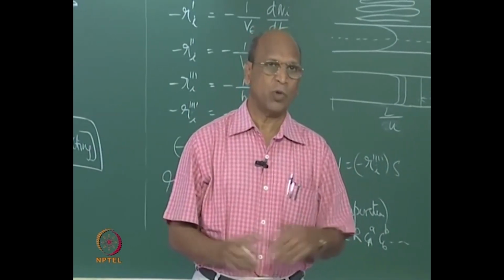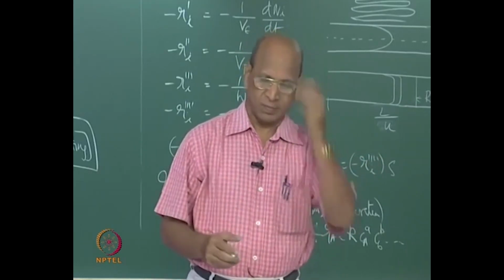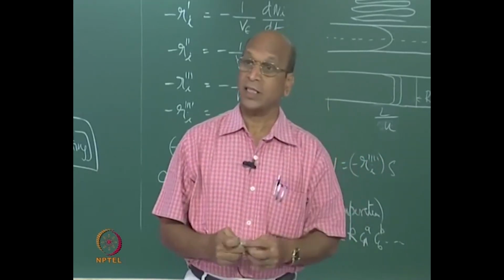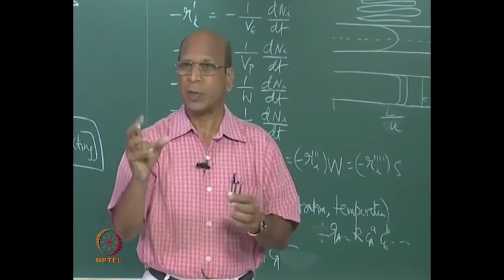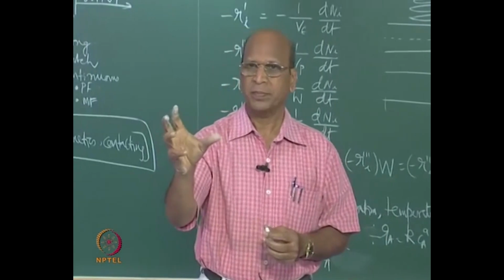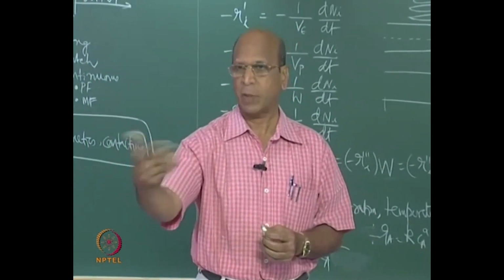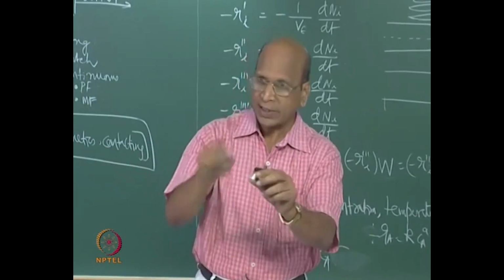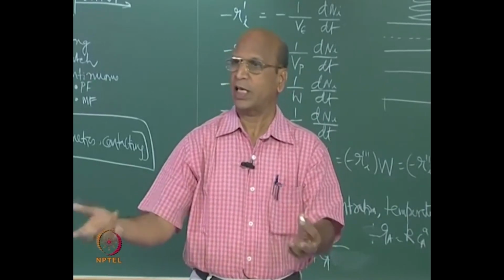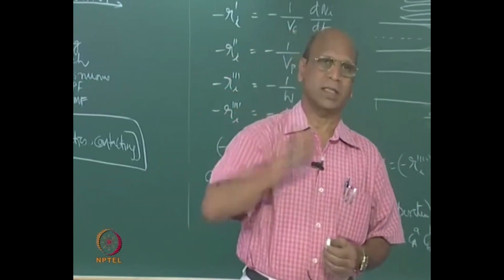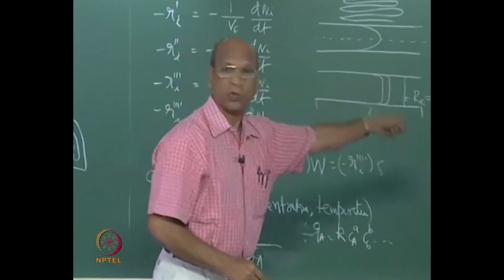So, that is the reason why you do not go for it most of the time, but we use mixed flow CSTRs in the laboratory to find out kinetics for gas phase also, because you are using a small reactor and a small amount of gas at different pressures or at atmospheric pressure, and you just find out what is entering, what is leaving, perfect mixing is there, then you can calculate the rate of reaction for gas phase reactions. Okay.